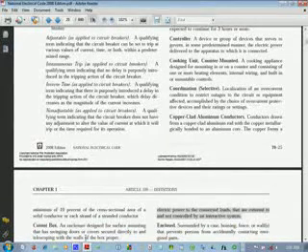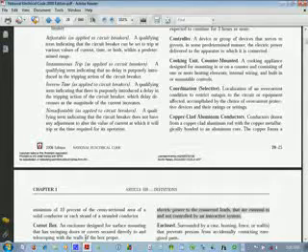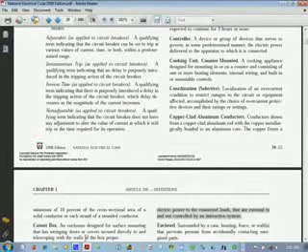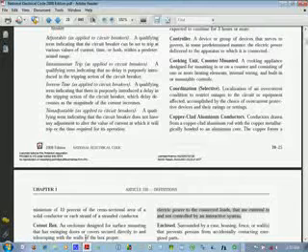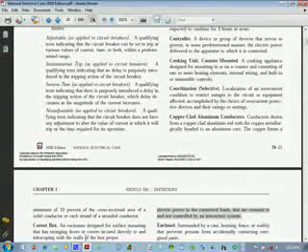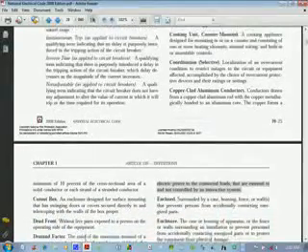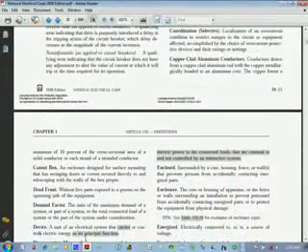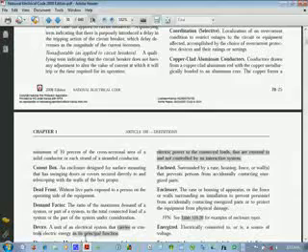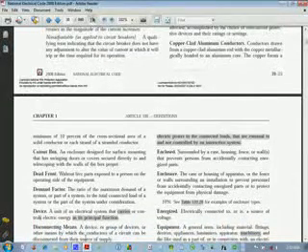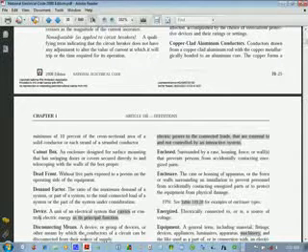Copper-clad aluminum conductors: conductors drawn from a copper-clad rod with the copper metallically bonded to the aluminum core. The copper forms a minimum of 10% of the cross-sectional area of a solid conductor or each strand of a stranded conductor.